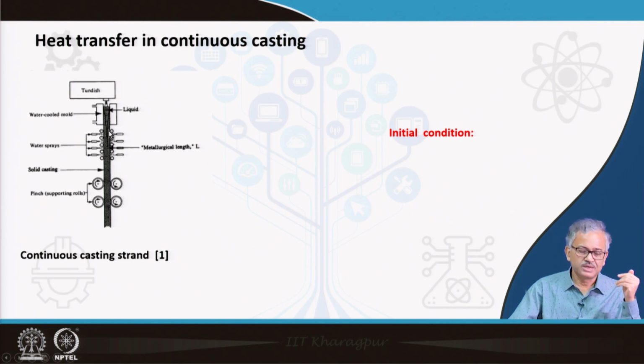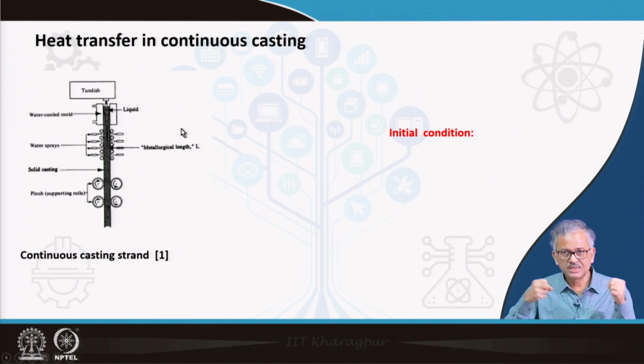It stays for a longer time, and that is why you require secondary cooling. When the casting comes out of the mold, you have secondary cooling such that the core liquid gets solidified.